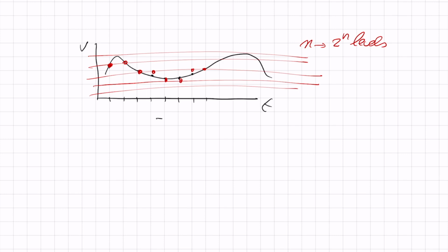Well, the sample time, Ts, is equal to 1 over the sample frequency. And the step size over here, that is 1 LSB, least significant bit. So in order to make a very good analog to digital converter, we like to have a very high sample rate, but also we like a lot of bits. So for the same window, say 1 volt, you want a lot of available levels of your signal.